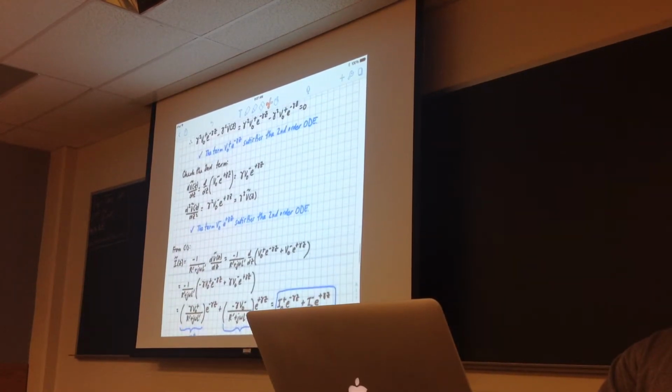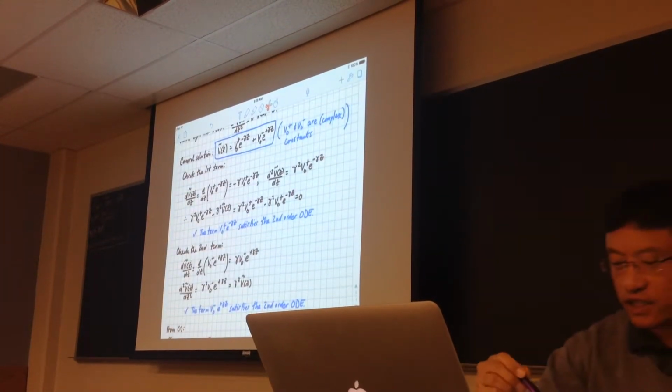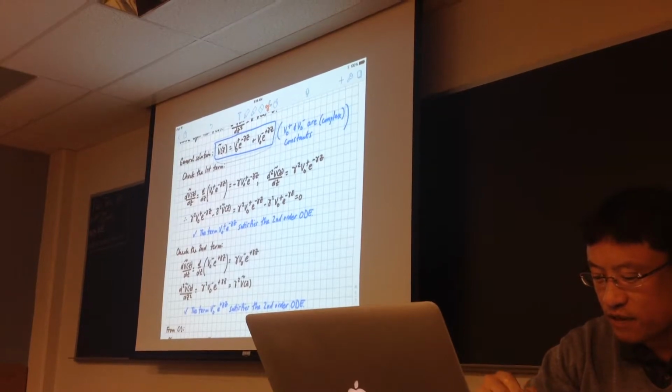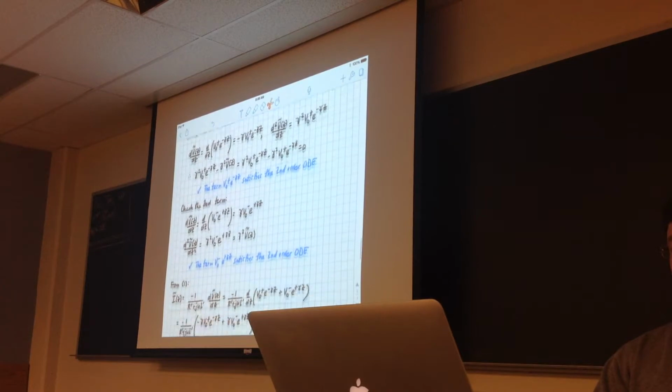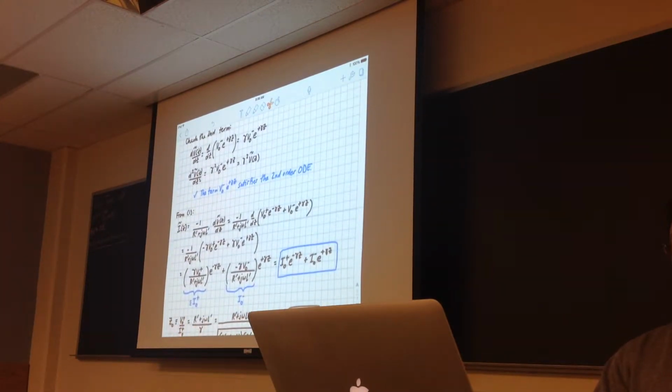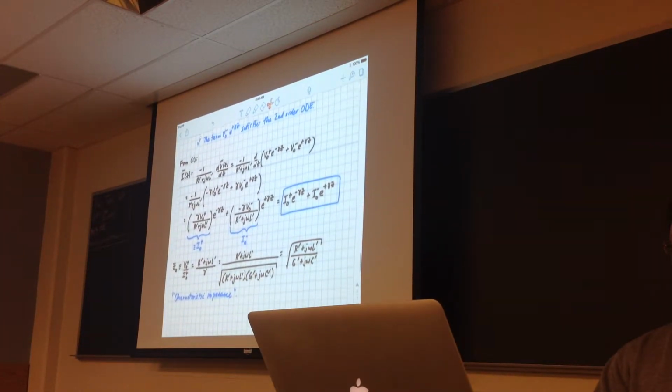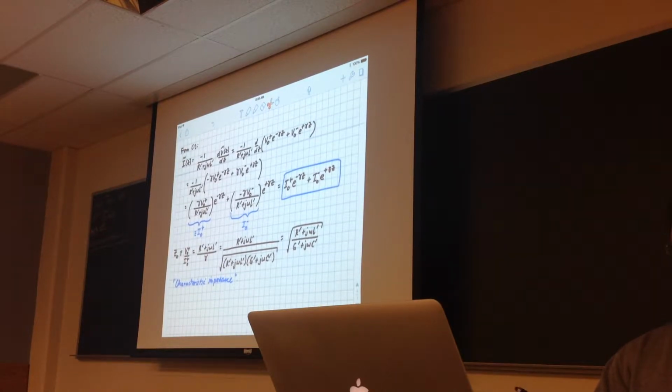We can write a similar equation. So voltage is V0 plus e to the minus gamma z plus V0 minus e to the plus gamma z. And we can write a similar equation for the current. Since we have the voltage, we can take the first telegrapher equation and just plug in the derivative of the voltage and then write a similar expression for the current. And that's what we did last time. You can see that the current I of z is I0 plus e to the minus gamma z plus I0 minus e to the plus gamma z. It has the same form.